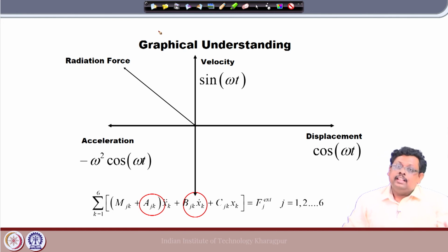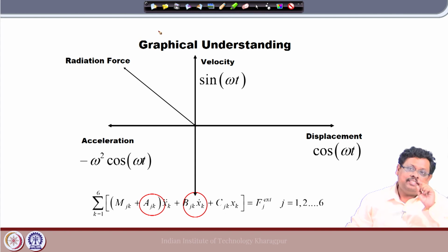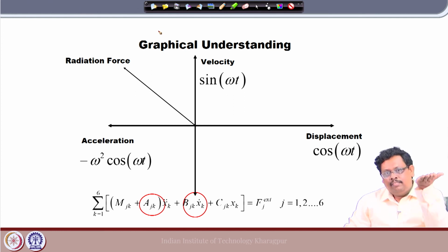Physically, why is this added mass coming, right? That is why I will tell you that in a very low frequency region, assume that you are actually on a beach and a wave is coming, and your body is just moving with the waves, right. If you remember, at that particular time there is no phase lag: when the wave gets to the peak you go up, when the wave amplitude gets to the minimum you go down. So your movement and the movement of the waves have no phase lag, right.